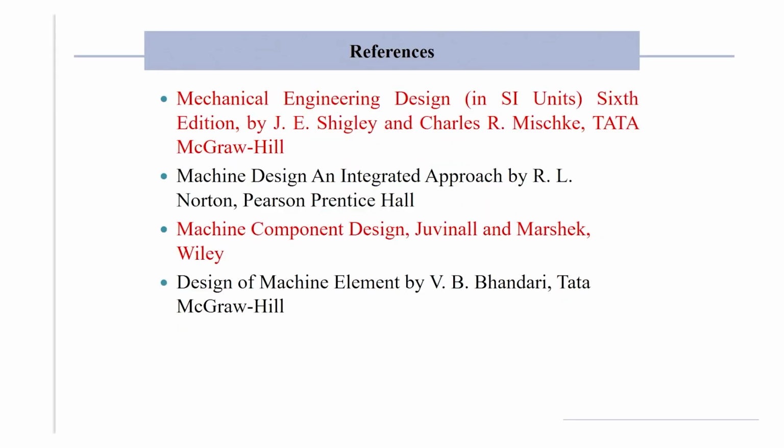So, we got the different parameters for the case of the given problem. The module which we obtained is 6, which is giving a satisfactory factor of safety for the case of pinion and gear under bending and surface fatigue. And the given material was nitralloy 135M, and its core hardness was taken as 320 Brinell.